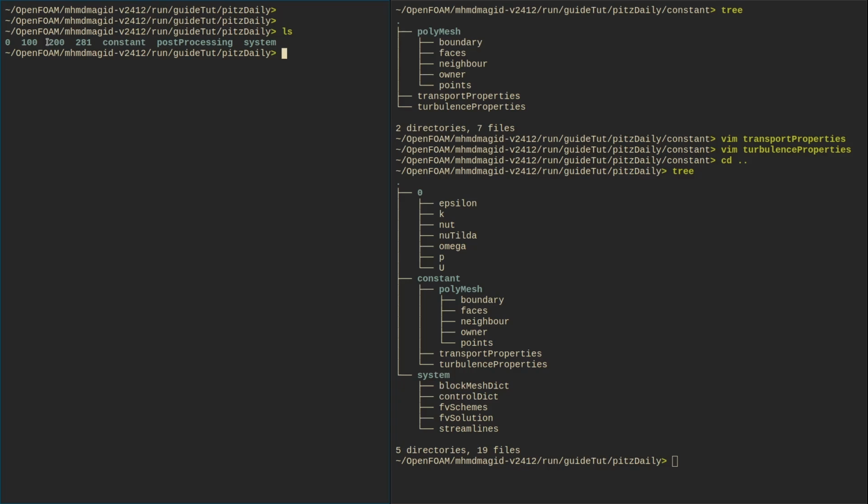Here you see the solution at different iteration. To export and visualize your data, you can create a new file with a specific extension, which is .foam, which can be opened by ParaView software. So you create this file by touch command, or you can use this trick here. Just write this operator and followed by the name of the file.